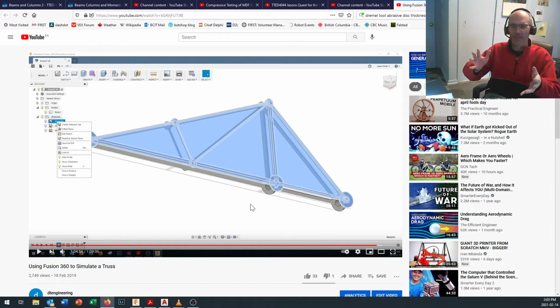And really what I'm getting at with that is: try some small samples, look at them carefully, watch how they fail, and then let's use some of the technical terminology to discuss how they fail and use that to make a nicer design. Use the high-speed video cameras built into phones right now, and get a good shot of your structure when you do your small scale test to see how it breaks. That will inform you on how to build your larger structure.